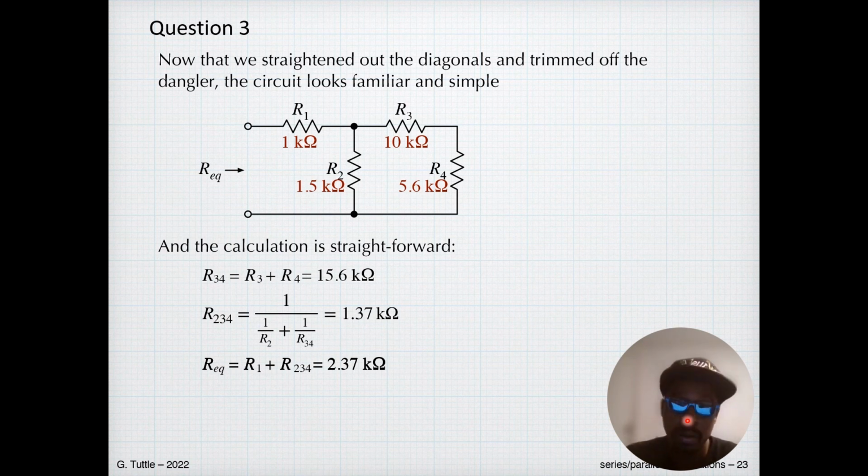If I go back to the previous slide, what we did in this slide was drop R5, because R5 does not suit the purpose of the circuit. If we look at it from the left side, the current does not go across the circuit, which would mean that nothing goes to that resistor, so it doesn't serve any purpose.